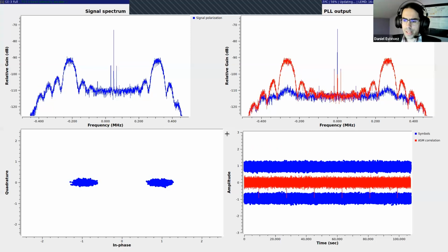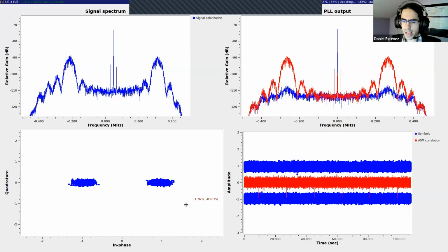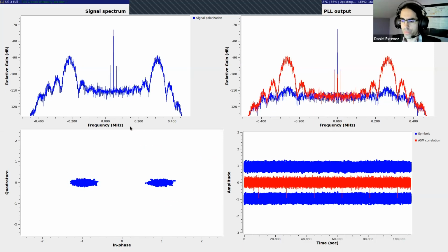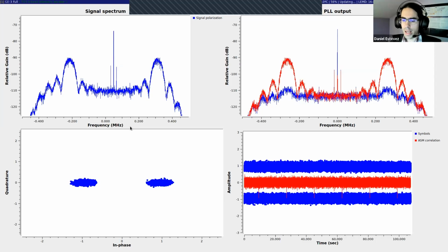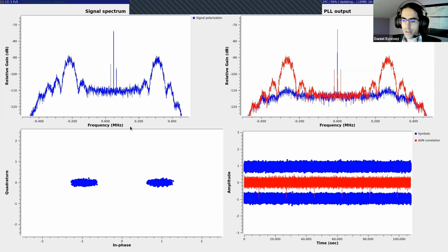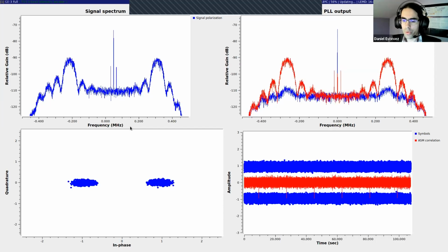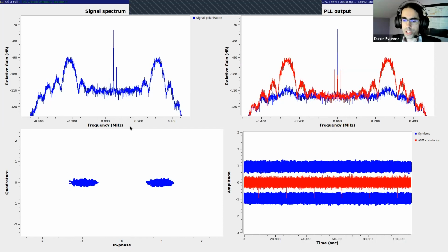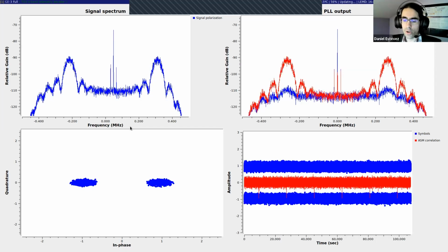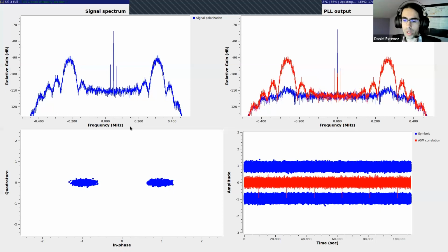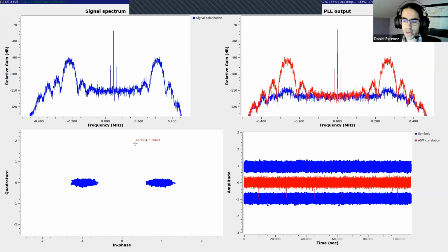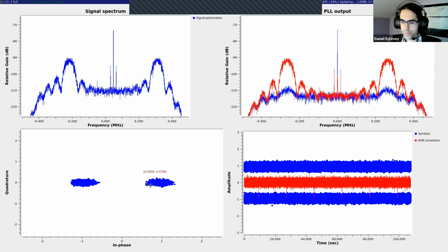Next thing we have is called the constellation diagram. So this is the output of the symbol synchronization. What we plot on a constellation diagram is the symbols. The symbols are the way in which binary digits or bits, which are 0 or 1, are transmitted as analog values. Here, -1 and +1. And we have these analog values and we also have noise.